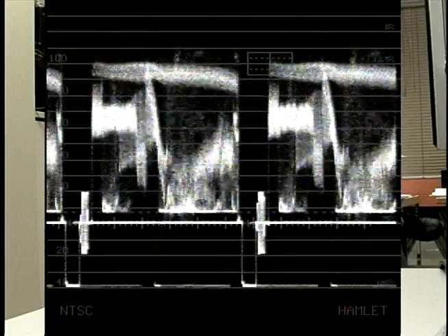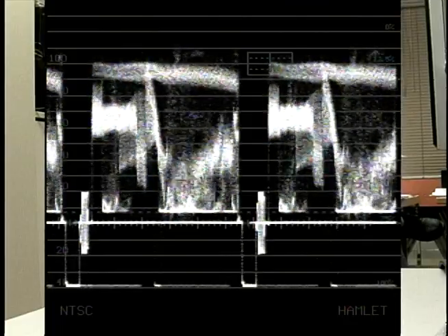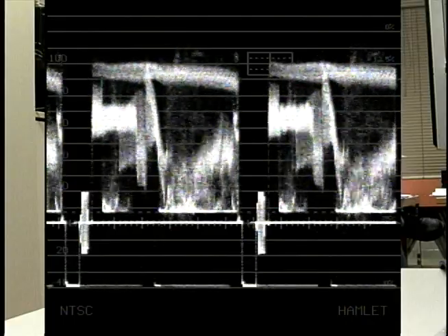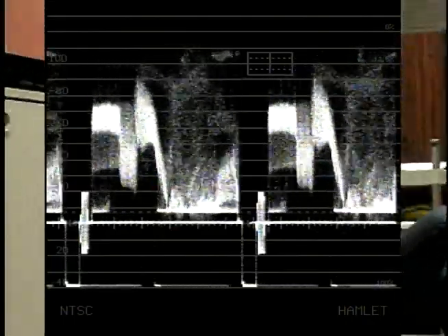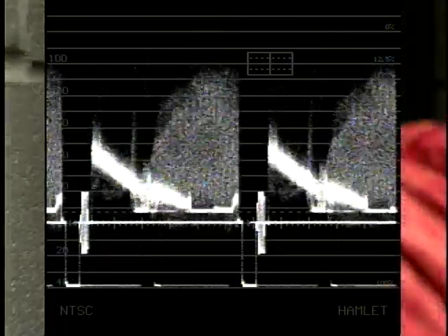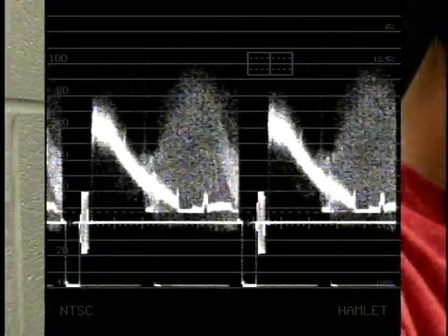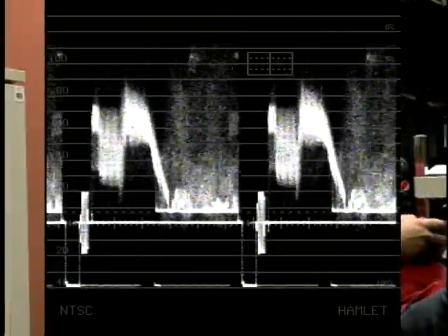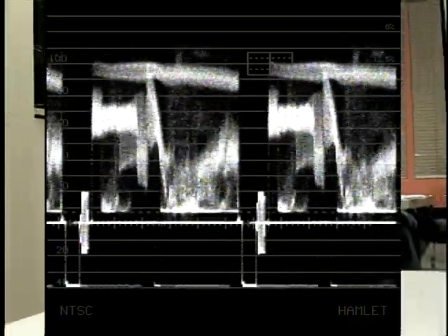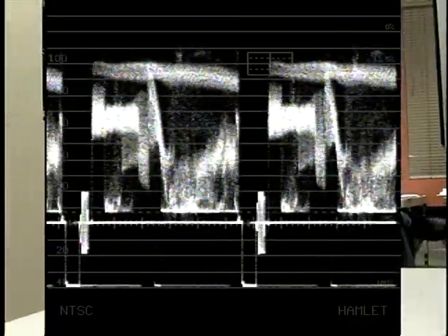If the black level is not near 7.5 IRE on the scale, adjust the camera's black level. Set the response control to L-Pass to view picture levels devoid of chroma information. If the whites are peaking too low, open the lens iris and